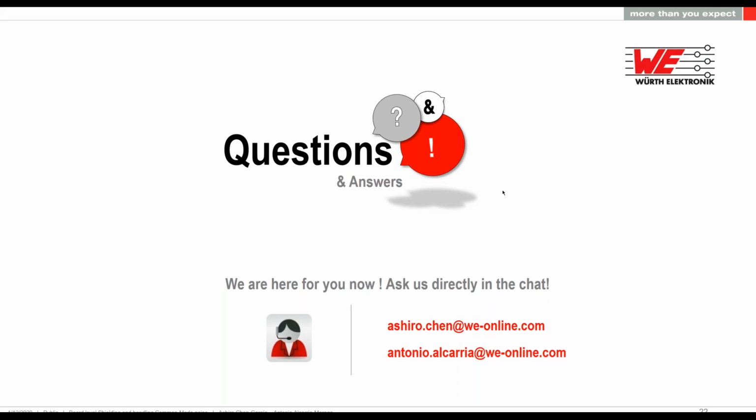Okay, thanks, Ashiro. And one attendee wants to know why you use 2 ground pins. Okay. Yes, I suppose he took a look at the website. You can see that apart from the 4 pads that we normally have in a common mode choke, in this case, we also have 2 more pads. So in total, we have 6, and 2 pads are ground.